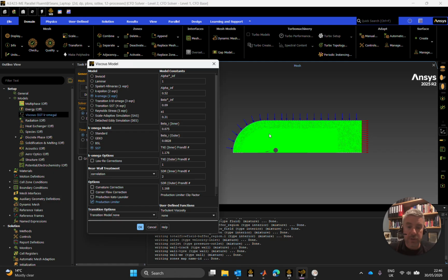But how that interfaces with the actual aerofoil itself could result in turbulent effects, or certainly transitional effects, even at them lower Reynolds numbers. So the flow regime itself, I would say, isn't completely independent of the surface that the air is flowing over, or the fluid's flowing over for that matter, and it's not completely dependent on the velocity, the density, the chord length, and the dynamic viscosity of the air.